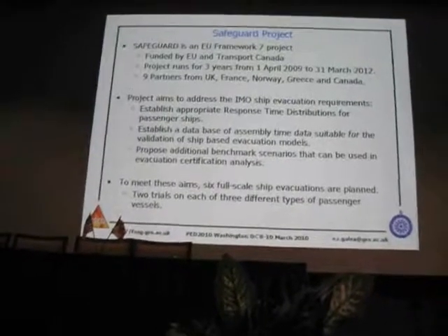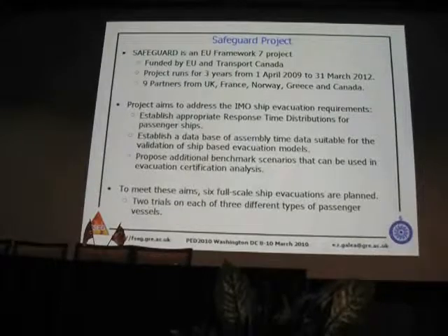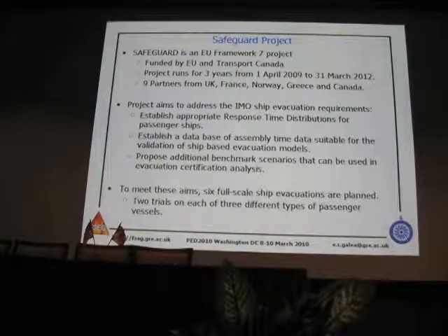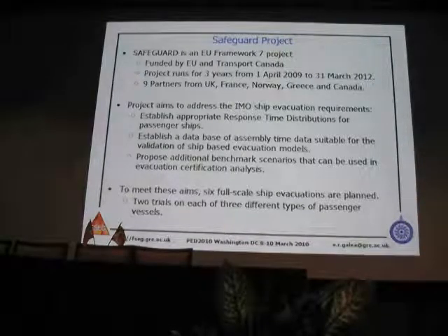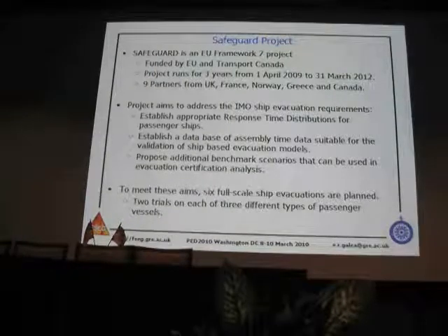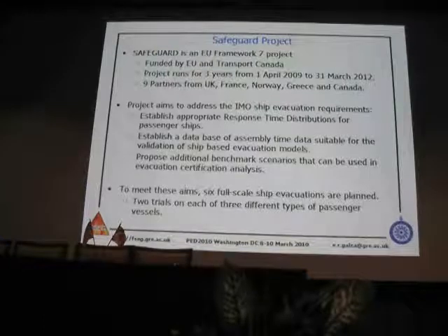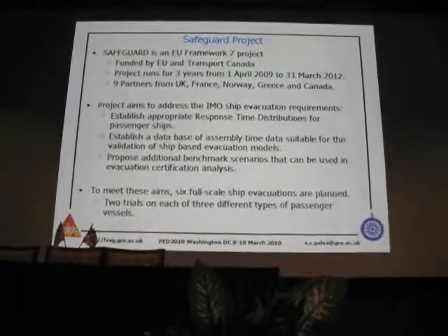The project aims to address the IMO, the International Maritime Organization, ship evacuation requirements that they've specified recently in one of the MSC meetings. And these are to establish appropriate response time distributions for passenger ships, establish a database of assembly time data suitable for the validation of ship-based evacuation models, and propose additional benchmark scenarios that can be used in evacuation certification analysis.